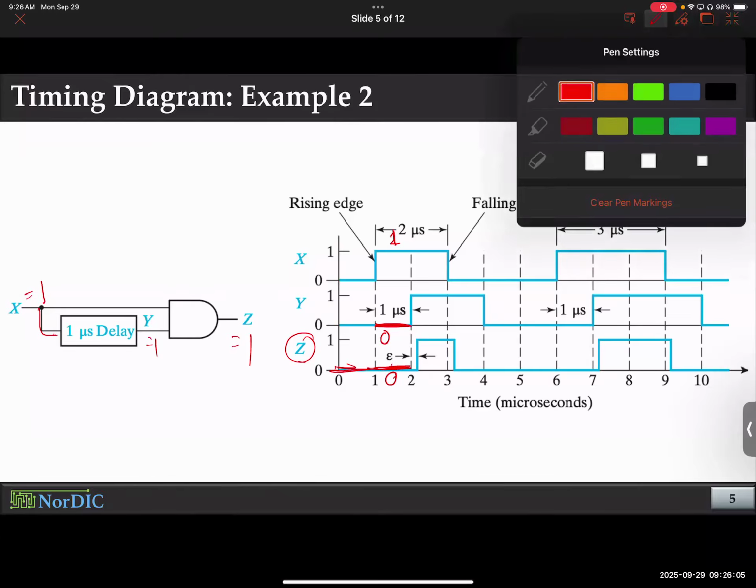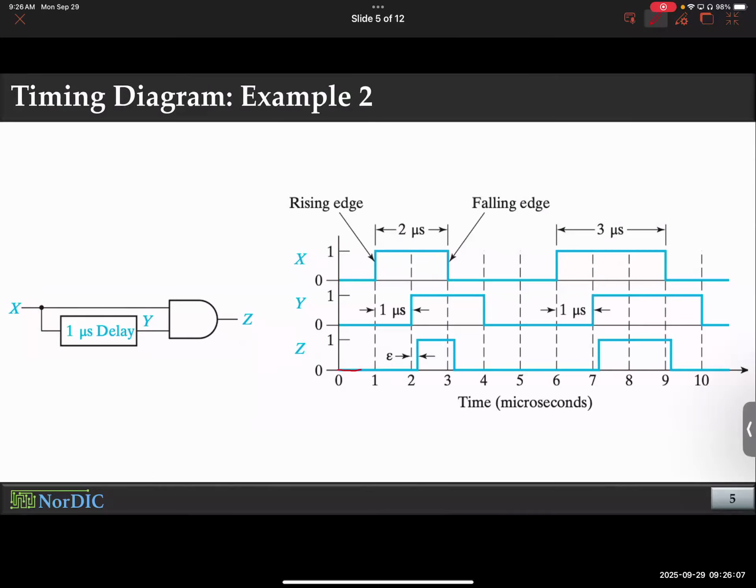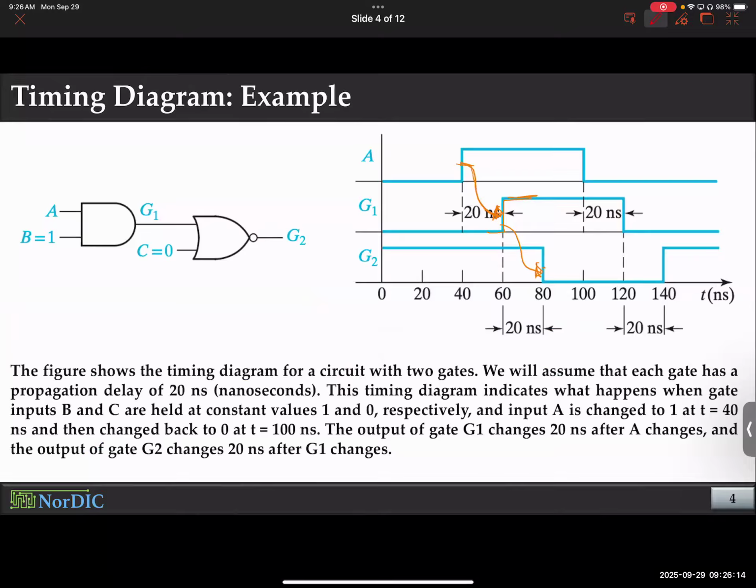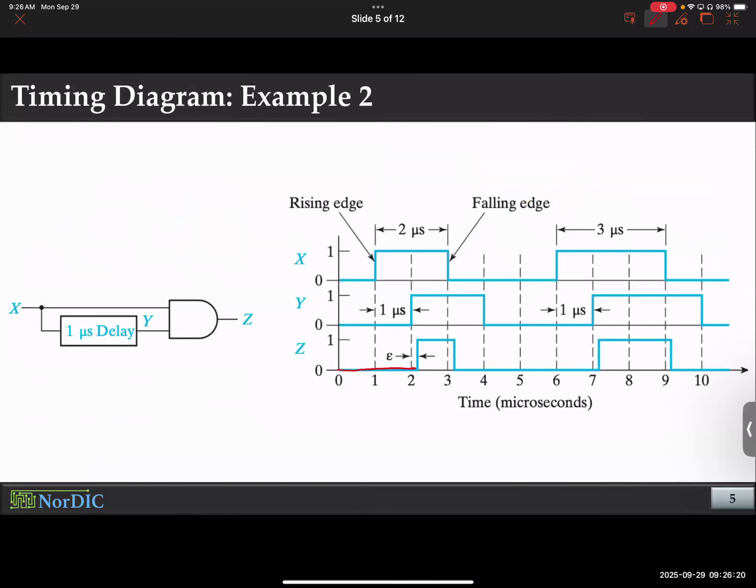All right. So my point is the exact same situation is occurring here. The difference between these examples and the previous one was you had multiple gates, one gate driving the other. What I'm trying to tell you is even if you don't have multiple gates, you have the exact same input and are trying to provide it through two different physical channels. That's the whole point. Even if you take the same input and copy it over multiple times, there will be different delays across different routes.